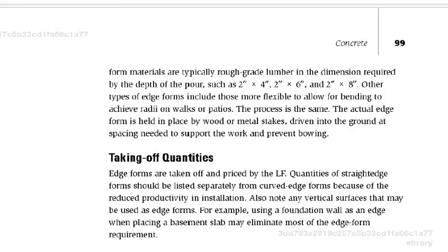Also, there are a lot of steel forms that you see that are used. Again, the problem with steel forms is that you have to protect them. They get bent and damaged, and then you're out of luck. Lumber also gets bent and damaged, but you can often cut good pieces off and use them for stakes. What you want to plan for is that you're going to use the timber, say, 3 or 4 times and dispose of it anyway.